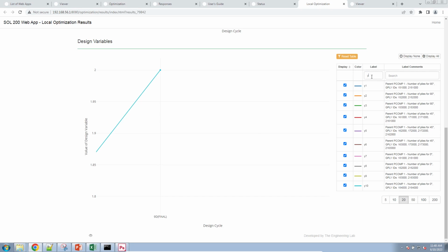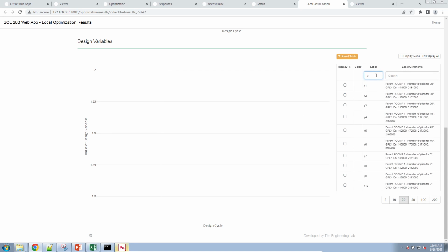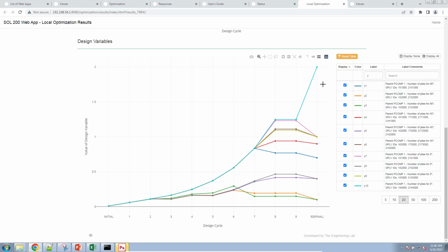Now, this ply elimination will sometimes increase the failure index. So you might accidentally go beyond the upper bound of 0.95 when you eliminate some of these ply shapes. This is okay because the stacking sequence optimization, which is the next tutorial, is going to bring back down or reduce the max failure index.